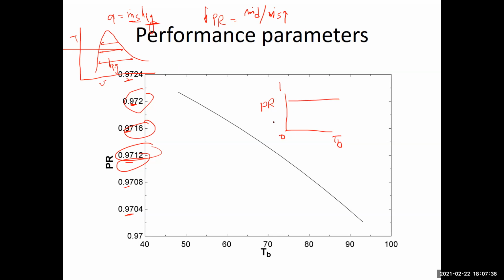But when it comes to single effect evaporation or multi-effect desalination, sometimes they refer to multi-effect evaporation as well, then normally we limit what we call the top brine temperature, which is our T maximum of the seawater, to a value of 65, and we don't exceed this value. So the example that we have solved today, when we started talking about a temperature of 75, is somehow an exaggeration, and the temperature should not exceed this value.